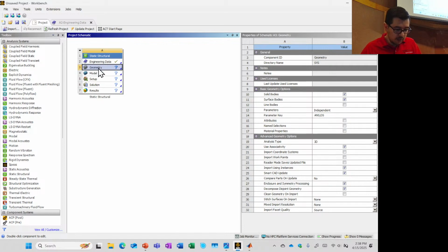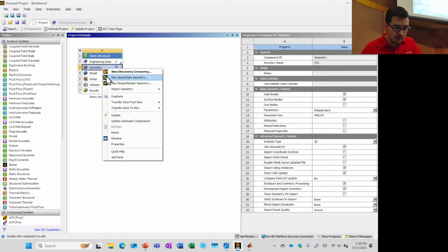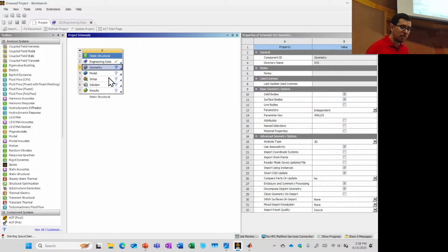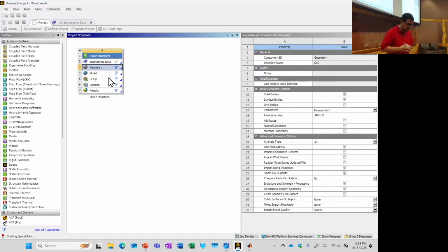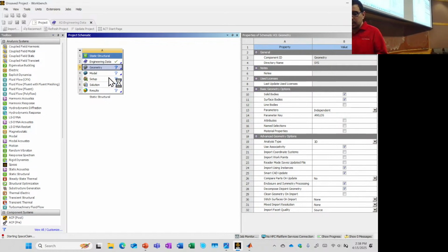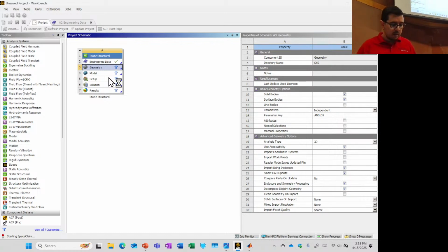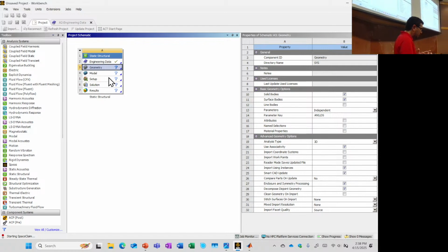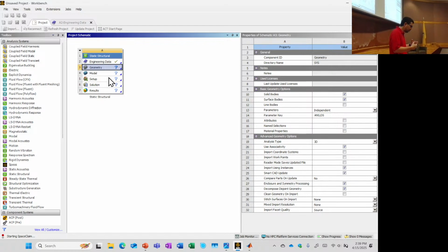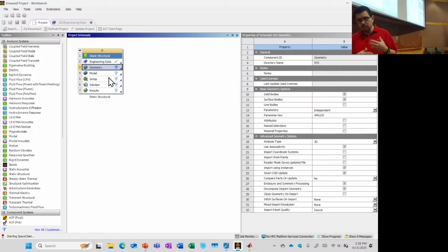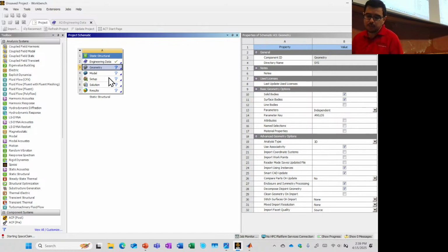I thought I right clicked. I'll right click again. Okay, and we're going to enter SpaceClaim. We're going to try. And so we have our kind of simplish geometry, which we've done before. It's not a bad idea to also make sure your units are right once you get into SpaceClaim. Mine is going to open into millimeters, which is just fine. When we did things in the micron scale previously, it was a good idea to go in the options and change that.